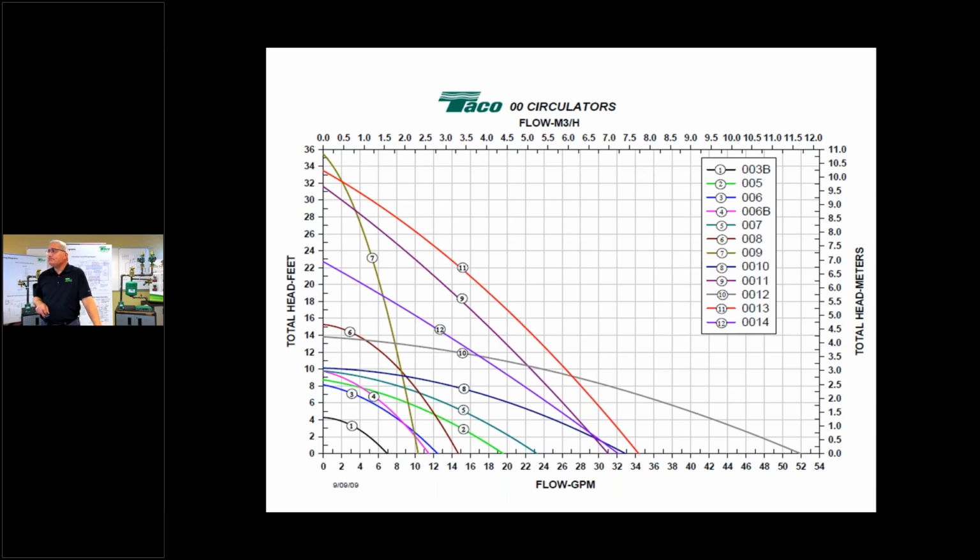Yes, sir. So we had a question, Jim, based on, you're talking circulators now, so I waited for you to get there. If you were to carry one SKU for a circulator on your service van, what would it be? All right, if I'm doing residential service, Taco makes the 0015E3, gives you the low, medium, and high settings.